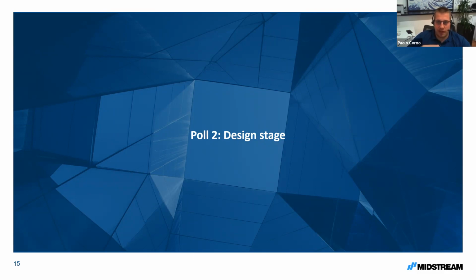It actually improved the uniformity. It all comes down to what photometric you're using. Some photometrics will require a higher tilt, some will work perfectly with lower tilt, especially if you're using asymmetric optics that are made to be installed flat to the ground. So zero tilt will give you good uniformity. But yeah, generally the concept is that it will affect the uniformity.